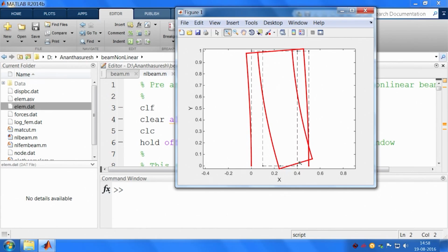That is called the cross axis influence. That is, you are asking it to move in a particular direction by applying force there, but the compliant stages that you have will not do that. They also will try to move in the other directions. That is the difference between rigid body mechanisms and compliant mechanisms. Compliant mechanisms, since they can move in other degrees of freedom, they do. So, they have this rotation also.